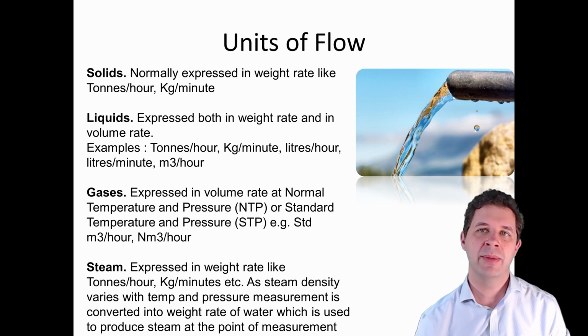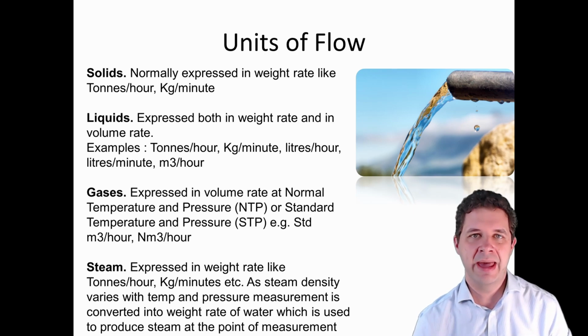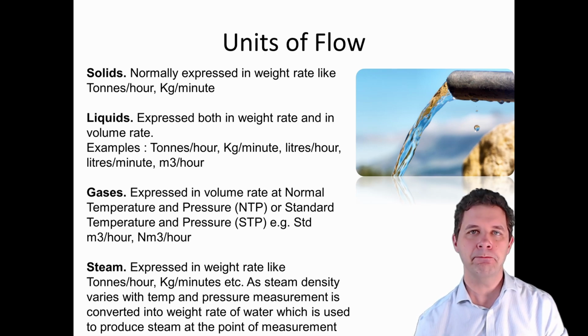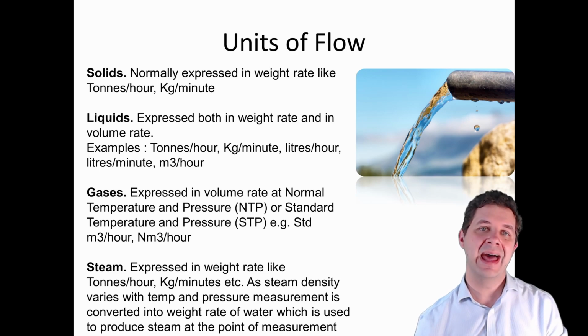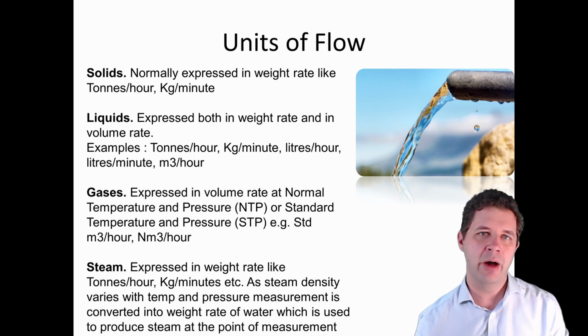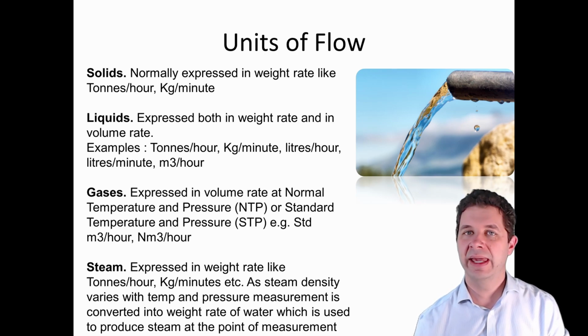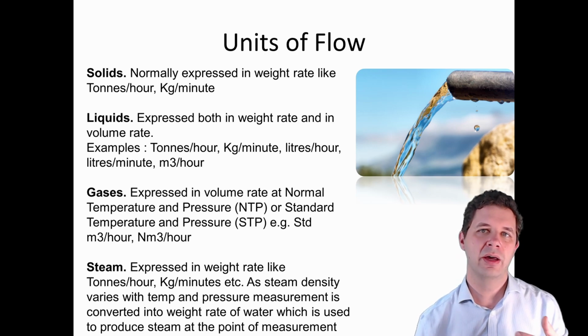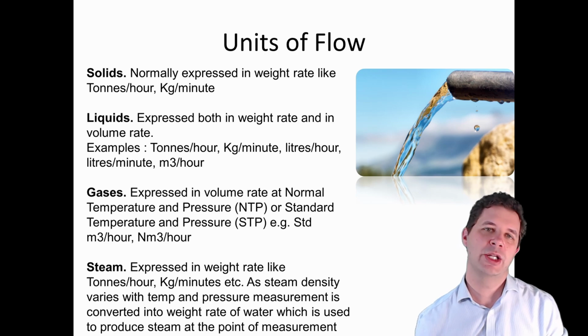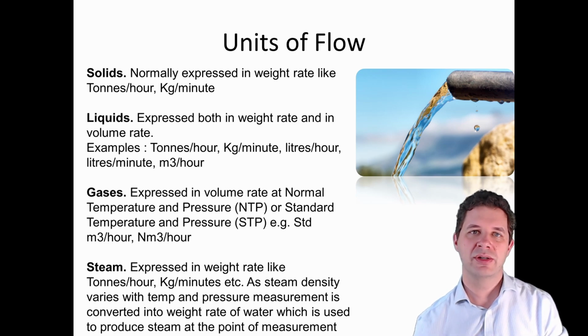So for example, if we're measuring solids, we might be looking at grams or kilograms per hour or tons per hour or something like that. If we're looking at liquids, we could be looking at a volume or a weight per unit time, seconds or hours or whatever it may be. When we're looking at gases, we're typically looking at volume over time. And we typically specify a temperature and pressure that we're dealing with during those things.